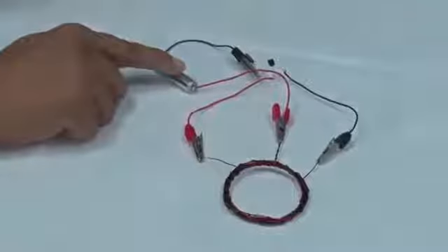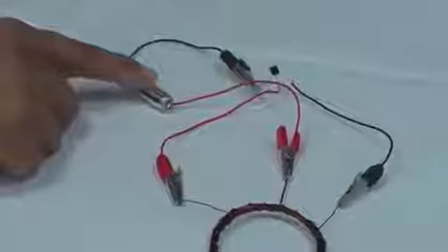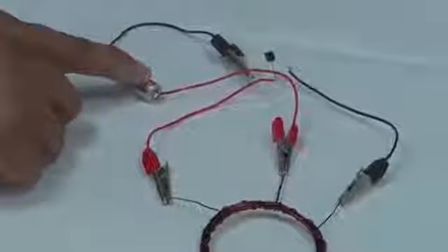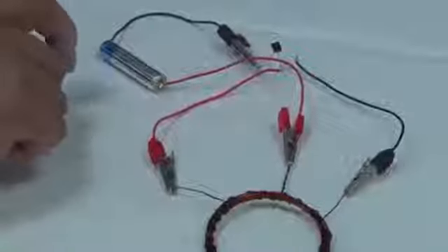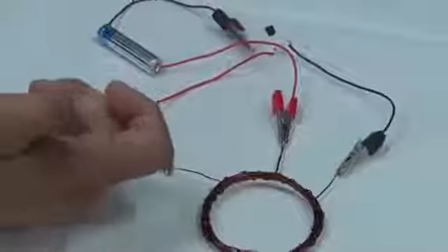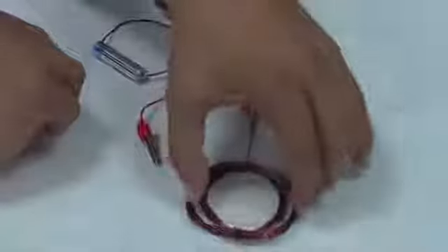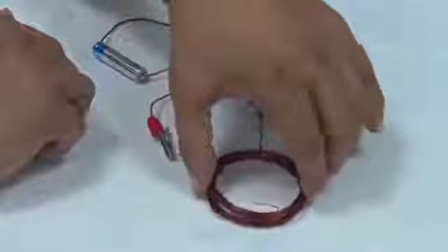but I am only using a single cell. It is a DC 1.5 volt. So, how come a DC 1.5 volt cell is able to create an alternating current? So, that means this is converting this DC to some kind of AC. Not exactly AC, but some kind of AC. Some kind of time variation is very much there, and strong time variation. Only then it can produce enough magnetic flux and change in magnetic flux to give rise to this LED current.